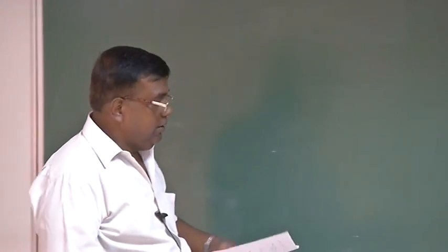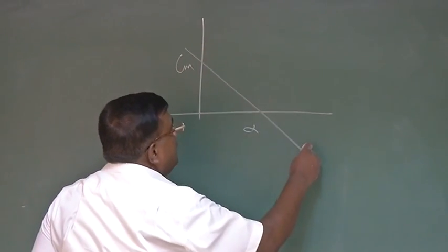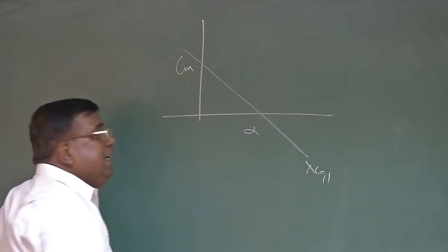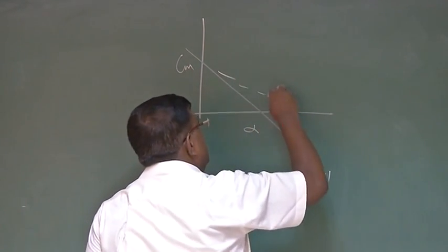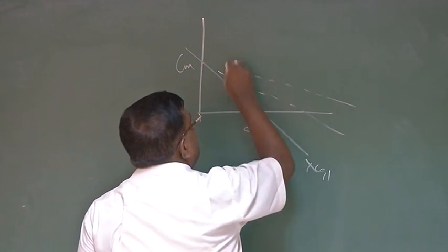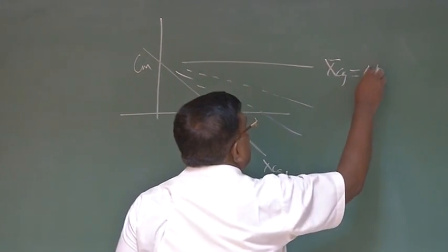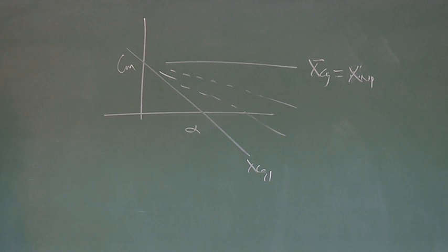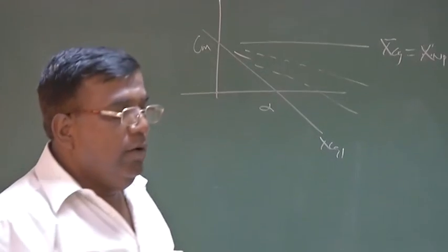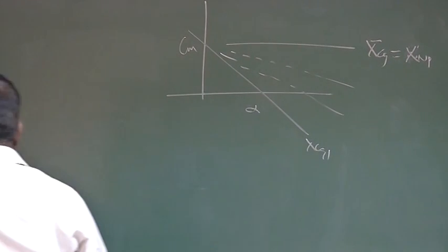Just to complete this part, we have seen one thing. If it is Cm versus alpha, and this slope is for a particular CG, if I take CG aft, then I know this slope goes on changing, and there is a CG location at which the slope is 0, and we call it the aircraft at this CG location has become neutrally stable, and that CG location where the aircraft becomes neutrally stable we call neutral point. So we will try to formulate neutral point also.